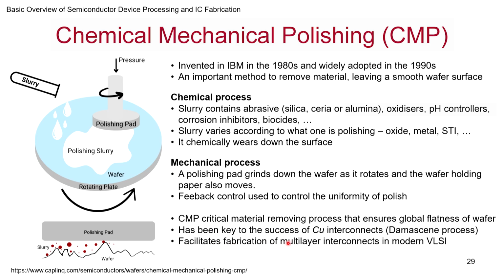It also makes multi-layer interconnect possible. Because we are having such flat surfaces, we can reliably build multi-layered interconnect structures in the back of the wafer. Okay, so CMP is a very crucial element in VLSI technology.